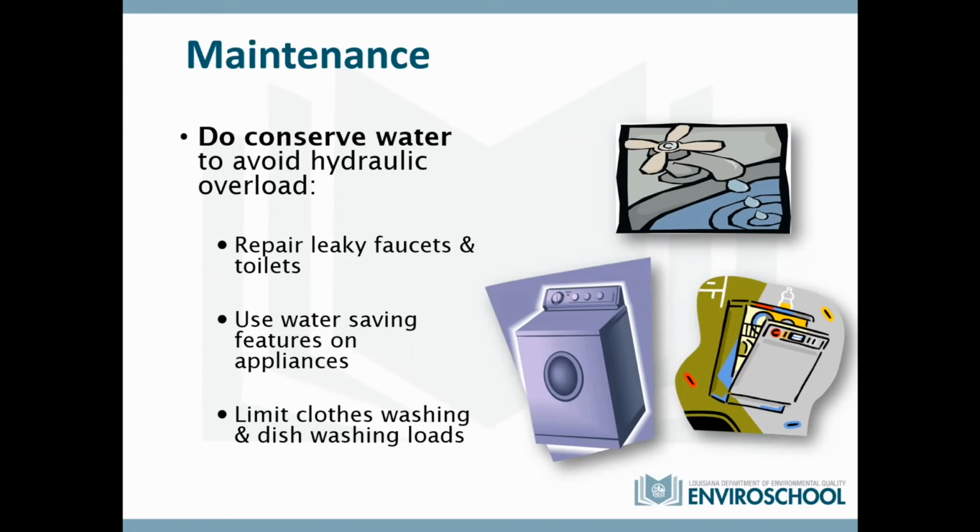Or if you have a field line, there's more of an opportunity for the solids from that sewage to get into that field line and clog that field line up. So what we say is conserve water. What we're doing now is the do's and the don'ts of sewage maintenance. So conserve water, and this is for everybody. Leaky faucets or running toilets, repair those. That's overloading your system. It's basically a constant drip of water going into it. Try to use water saving features on your appliances. And when it comes to washing your clothes and your dishwashing, try to spread those out. Don't do it all in one day at the same time because that's going to overload your system.